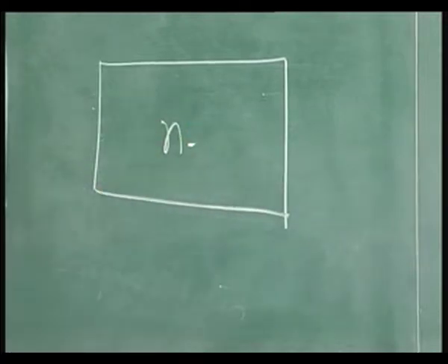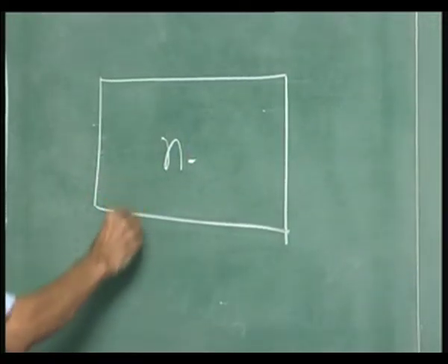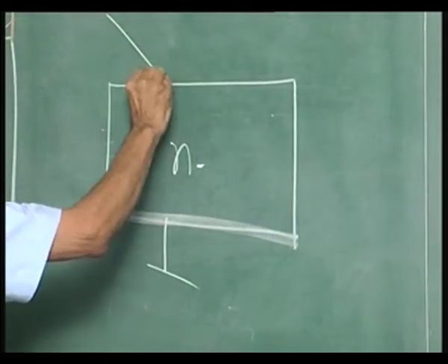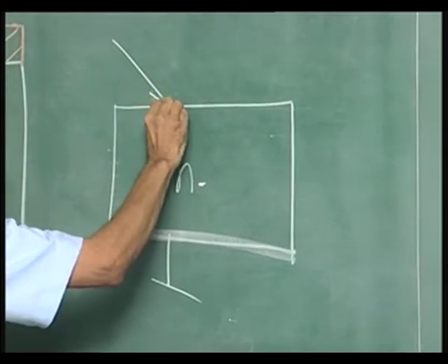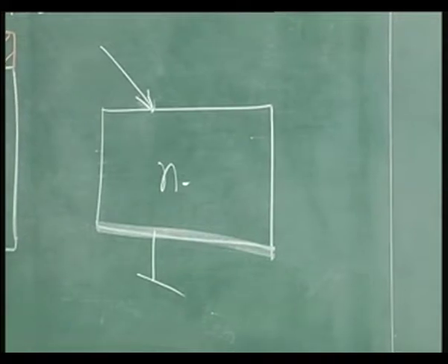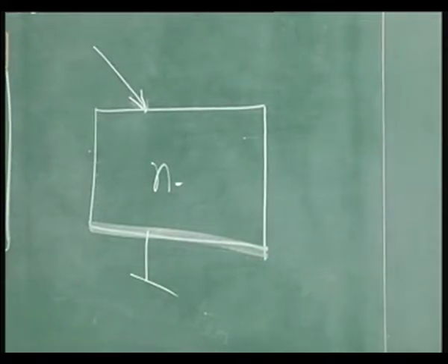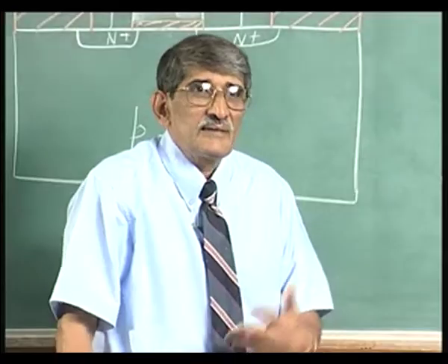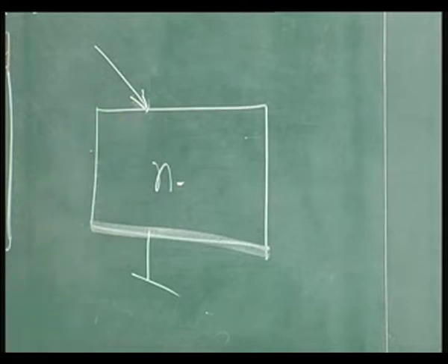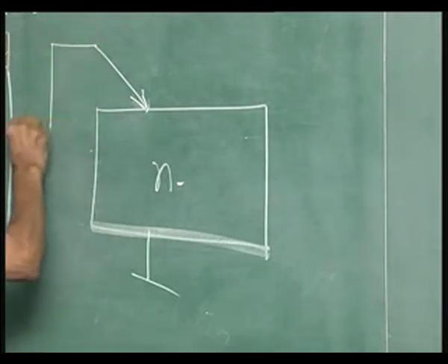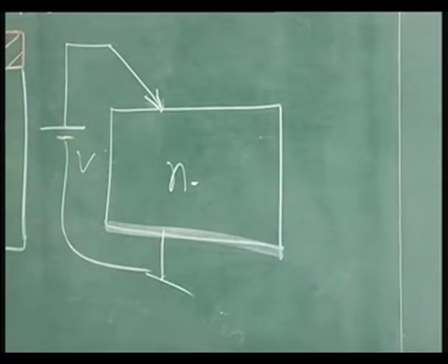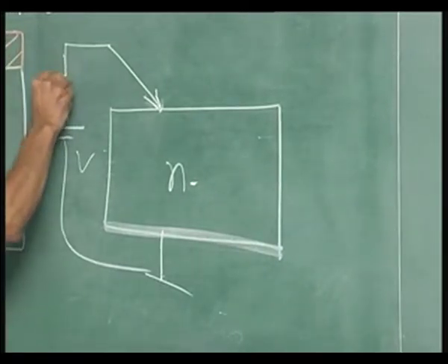N-type silicon, germanium they put. Then what they did was, they put a contact here, back side. Then they put a probe. Heat it locally, it becomes a sort of PN junction, like a point contact diode. Old days, all the detectors were point contact diodes, that type of thing. So, this is actually virtually like a P-type material. And then they applied a voltage between the two, okay, a small voltage. Maybe they put a resistor in series, so it limits the current.